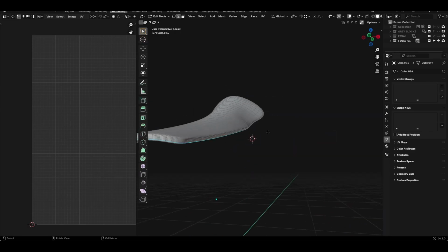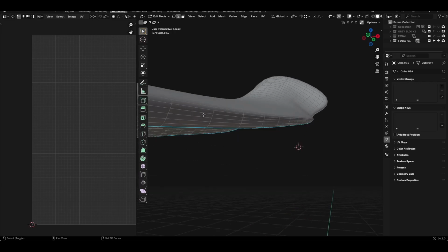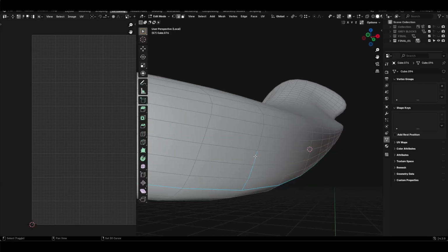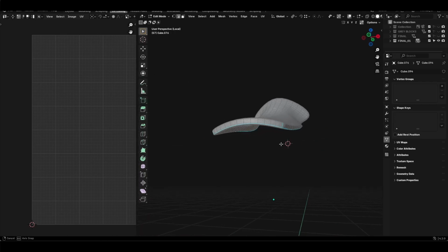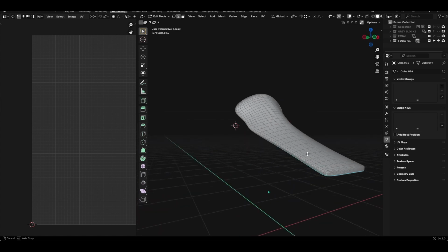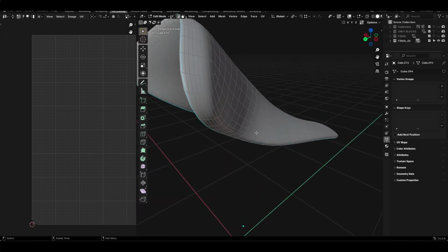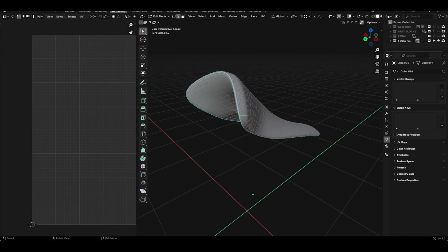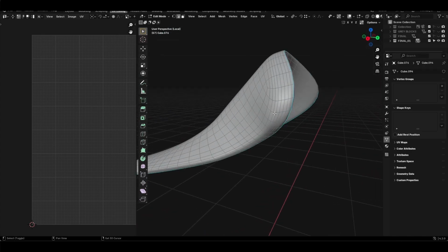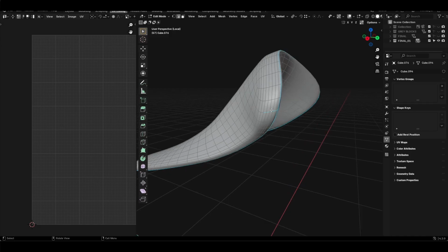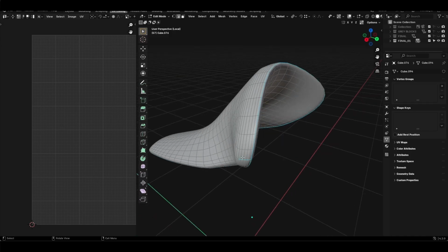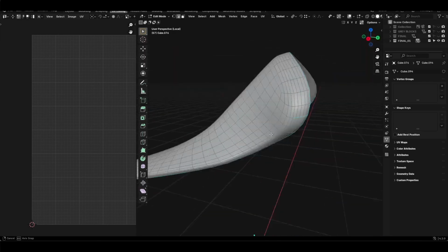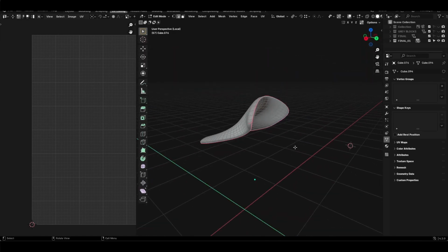I'm gonna do the same thing on the other side, because if I don't cut this thing into half, the UV will be stretched out like crazy. Same here. So the texture will be distorted if I'm not going to cut this. So what will happen is this part will be split and avoid the distortions. Okay, so right click, mark seam.